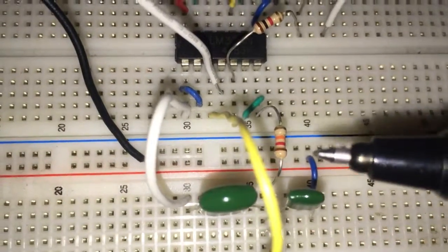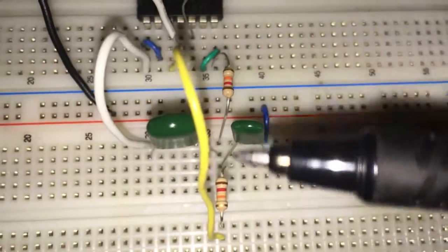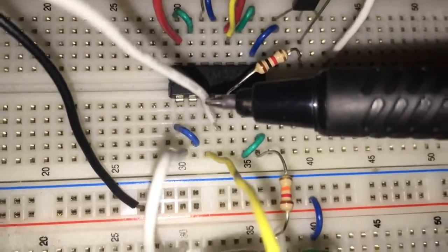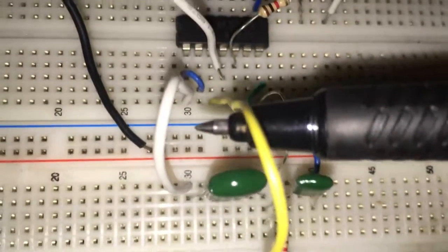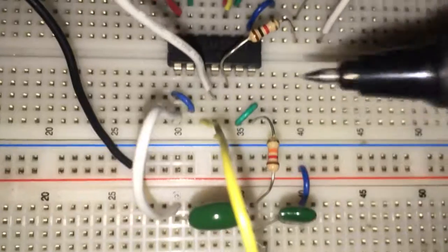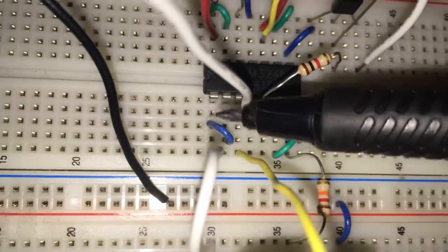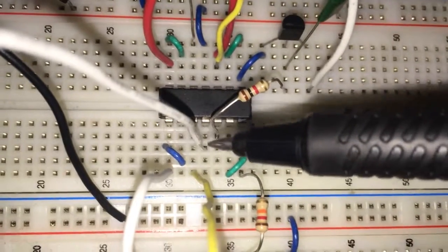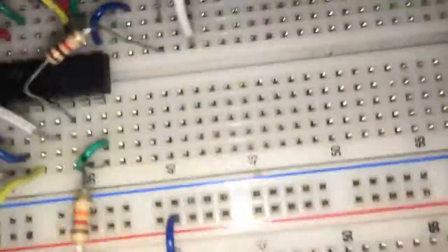The smallest capacitor is connected to ground. This end of the resistance line is connected to the positive input of the last op amp. The larger capacitor is connected to the output of the fourth op amp. As we have seen in the other operational amplifiers, the negative input is connected to the output of the op amp. This line here is our positive input voltage, our voltage source for the op amp.